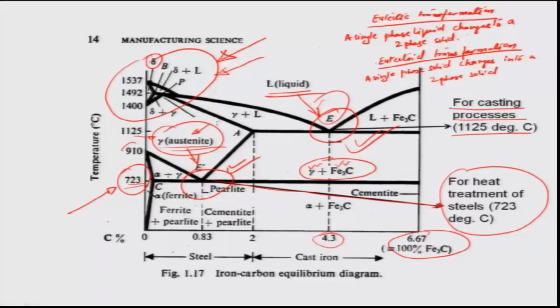And then you are going to convert that into pearlite, which is again a sort of two phase solid structure. So, it is a combination of cementite and ferrite, being the alpha iron, which we commonly know as the BCC crystal, and cementite is Fe3C.